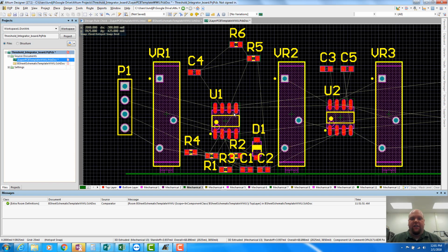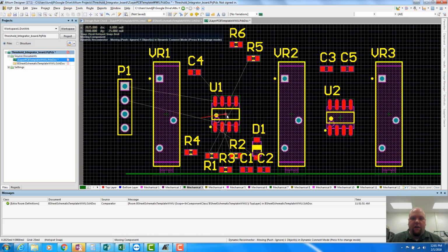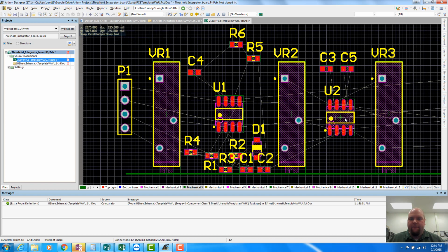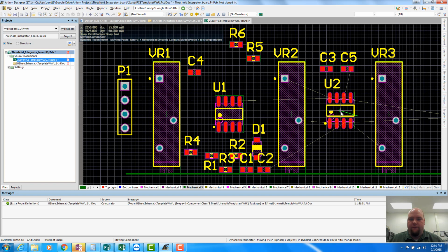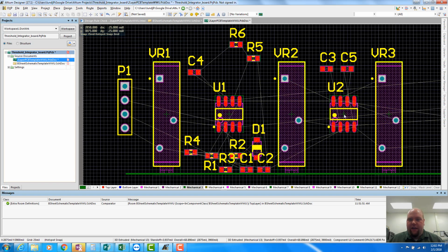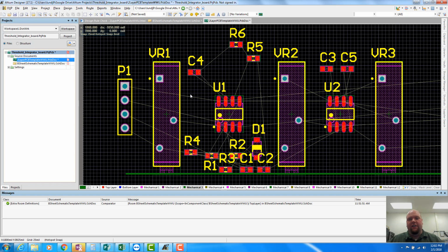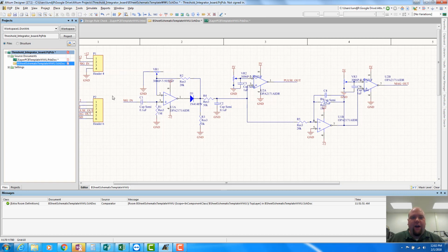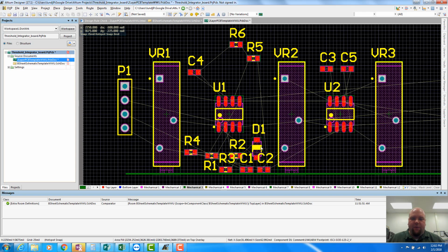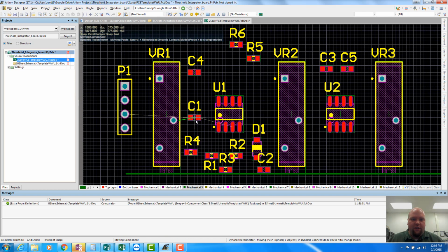And I like to rely pretty heavily on the schematic when doing this, because the schematic really tells us where these signals are moving, where the adjacencies are. So we can use air wires, but boy, sometimes we save ourselves a lot of effort if we just route it in the direction that we have here. So our signal's coming in initially through C1, so we probably want C1 to be kind of close to our signal side of things, like right here-ish.